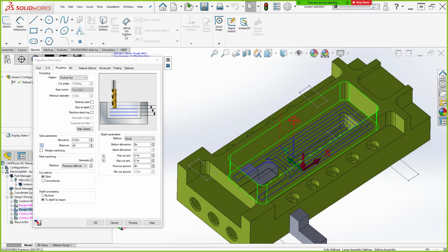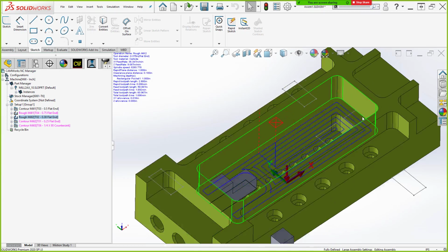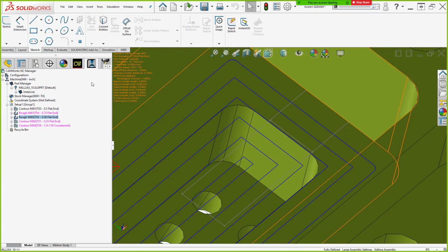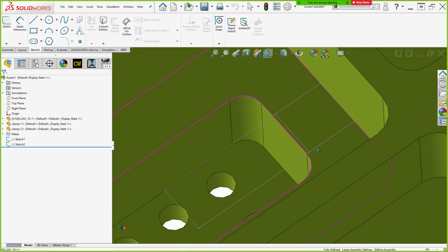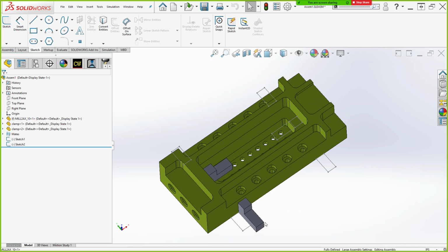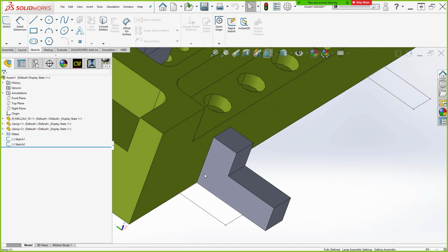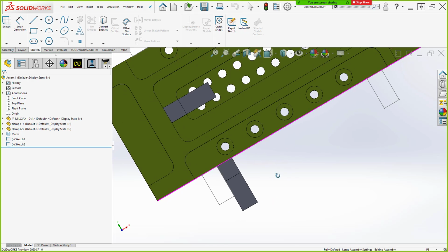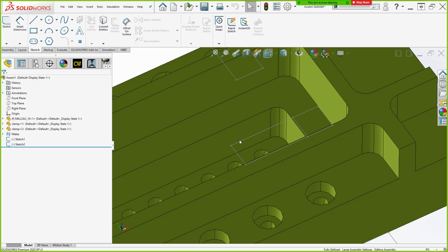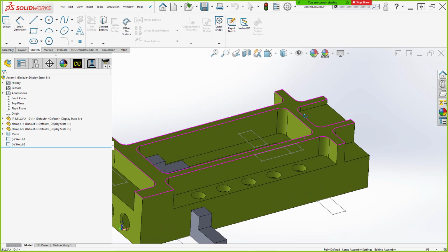So something I've been able to do is use multiple contain areas. So I have two sketches here. I have a rectangular sketch and then this square sketch, which is a simple representation of my clamp here, right? Looking down on the profile of it. You can set one height for the large rectangle and another separate height for the square itself when you do a void area.